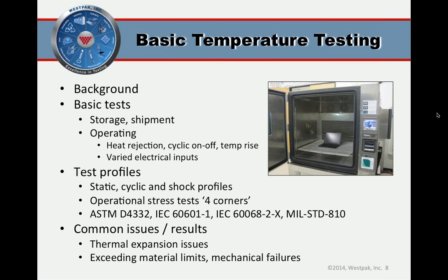The reason is that most materials expand with rising temperatures and they'll contract with cooling temperatures. That's the nature of the beast. And sometimes this change is exaggerated, sometimes it's subtle. It's always stressful, primarily because when you have 2 different materials fastened together, they'll expand and contract at different rates. This is bound to produce stress sooner or later. Something's got to give. Some popular materials such as aluminum tend to have very high expansion and contraction rates with temperature than other common materials, and therefore stress is common with aluminum structures and components.